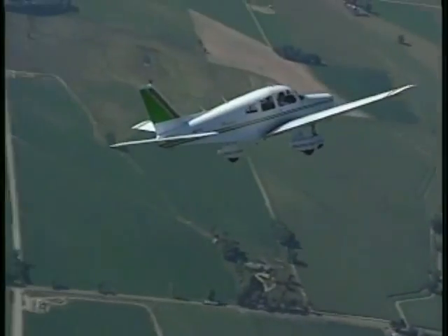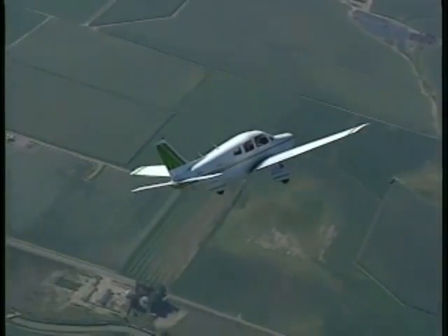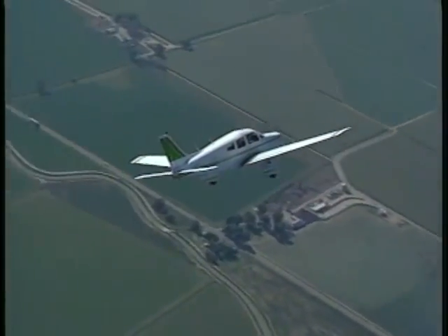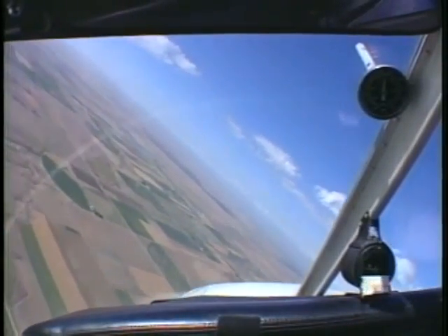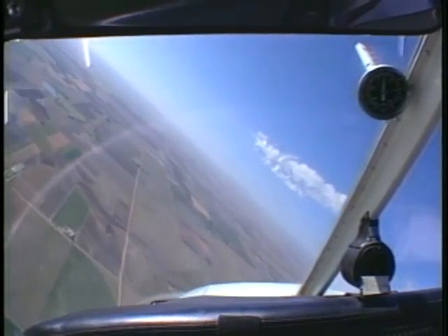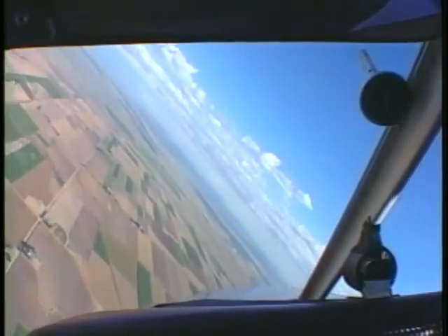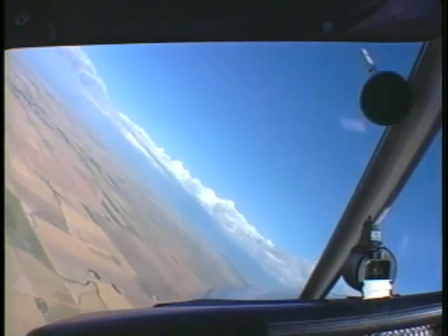When you perform any maneuver in which high bank angles are used, it's important to maintain an awareness of the load factors imposed on the airplane. Any improper use of the controls can abruptly increase the load factor, which can lead to an accelerated stall or structural damage. In addition, pulling back on the control wheel to reduce excessive airspeed may actually tighten the spiral. The proper procedure to correct for excessive airspeed is to decrease bank angle, then apply back pressure.